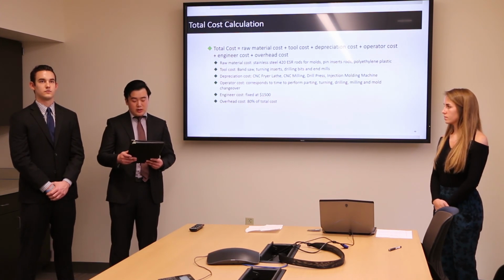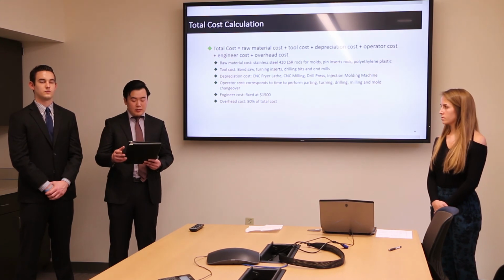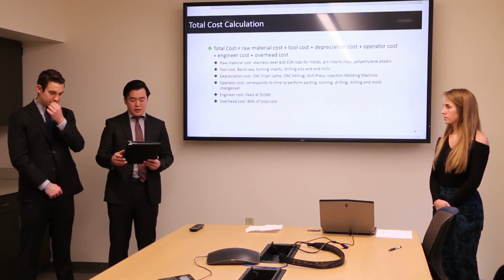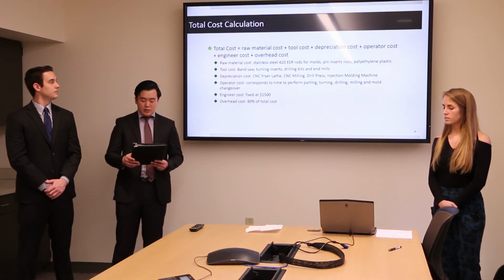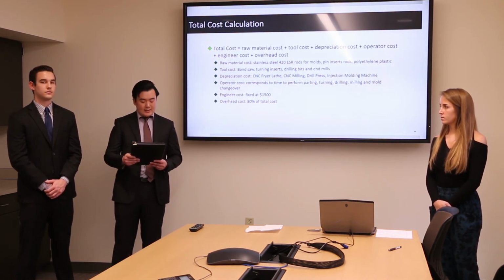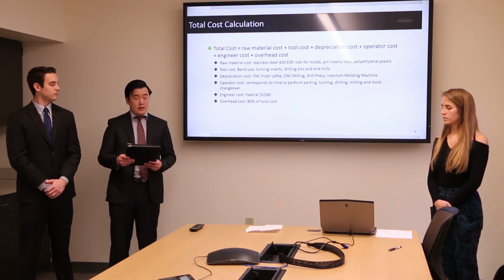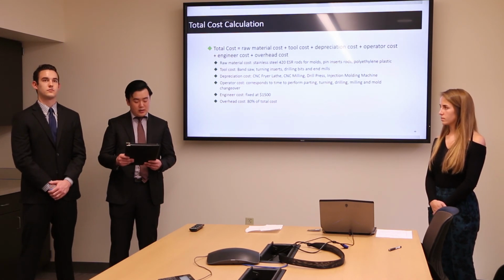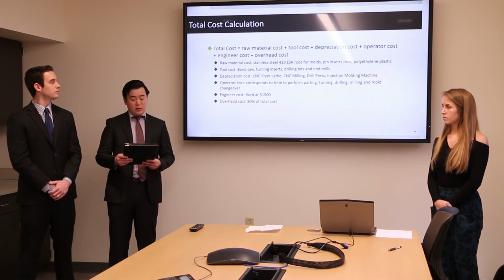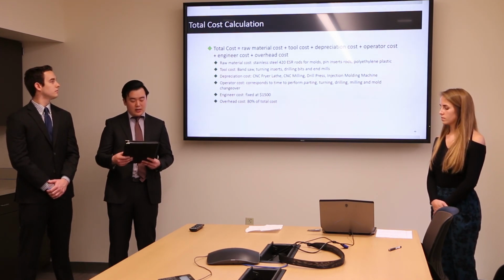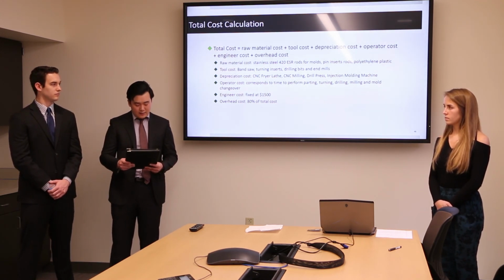In this project, all the machines used have a corresponding depreciation cost and the same operator cost except the injection molding machine. In the conversation with Mark, the MGL lab manager, we were provided with information that in common manufacturing scenarios, an auto injection molding machine is applied so that no operator will be needed for the injection molding cycle process. Accordingly, in this project, the operator cost is only applied on injection molding for the constant 40 minutes mold changeover time for each design.